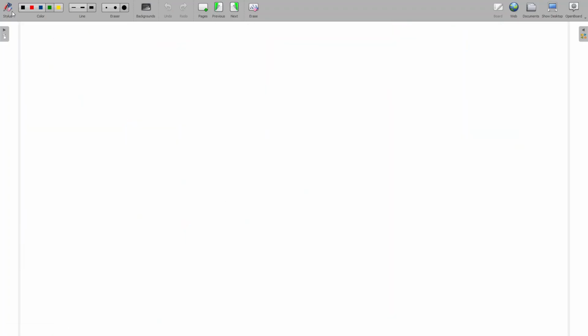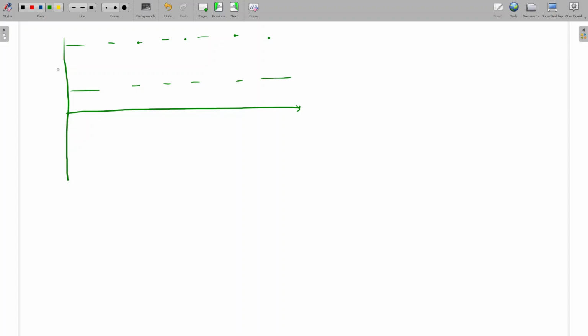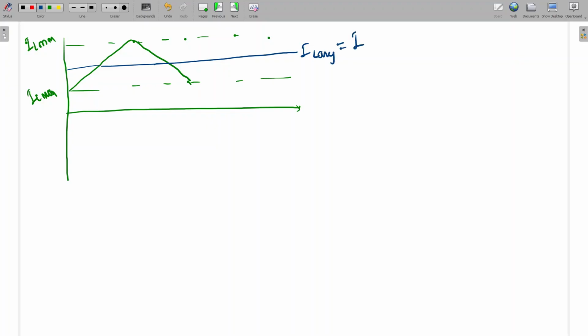So the inductor voltage waveform you can draw. One second. The inductor current will be a triangular waveform. Some maximum value will be there and some minimum value will be there. So it will charge like this for the on duration and then discharge, between IL max and IL minimum. And what will be the middle value? The middle value will be the IL average. This value only will be the I naught average. So how much will it be? 25 amps.